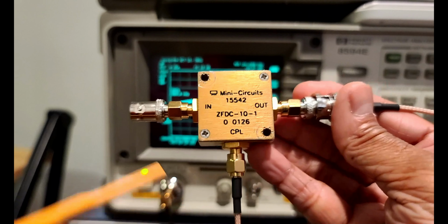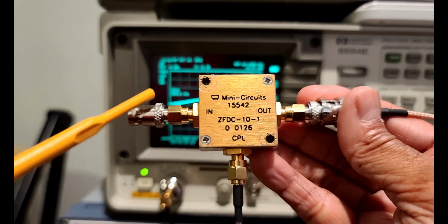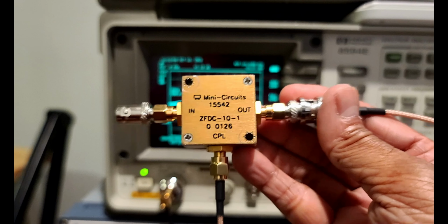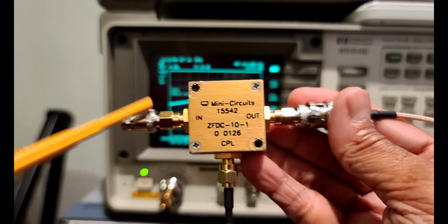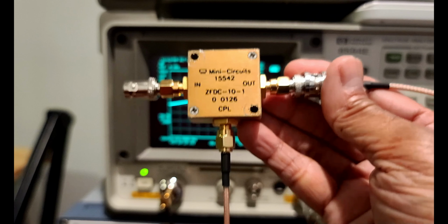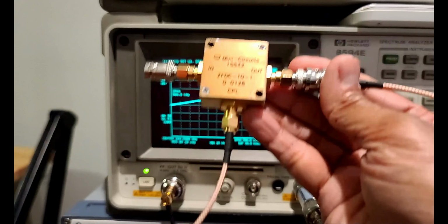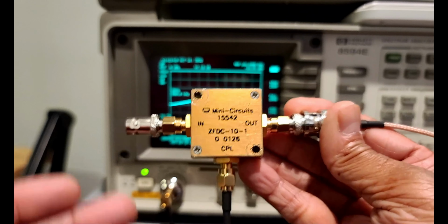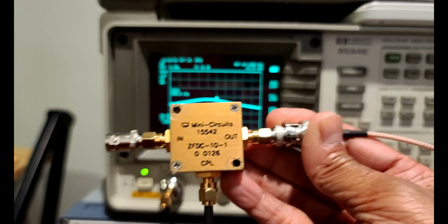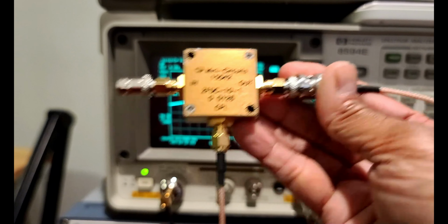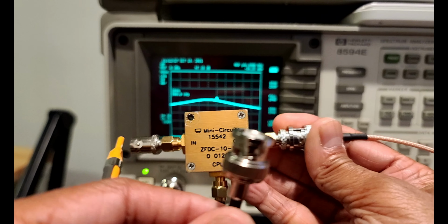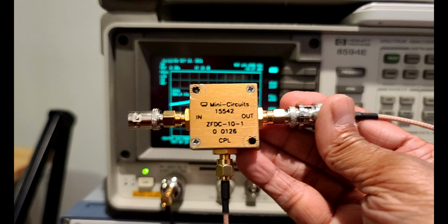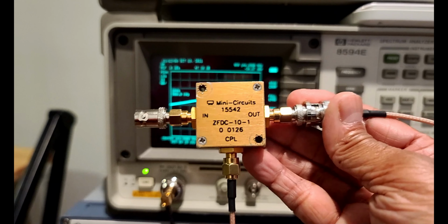Let's say, as an example, you had a 2-meter antenna on the input port end and you fed through a 144.39 frequency. If that antenna is tuned to 144.39, the reflected loss coming out of the coupled port will be minimal. If the antenna is not tuned properly to 144.39, there will be a notable loss that is realized by the coupled port. So that's the high-level summary of what this idea is based on.